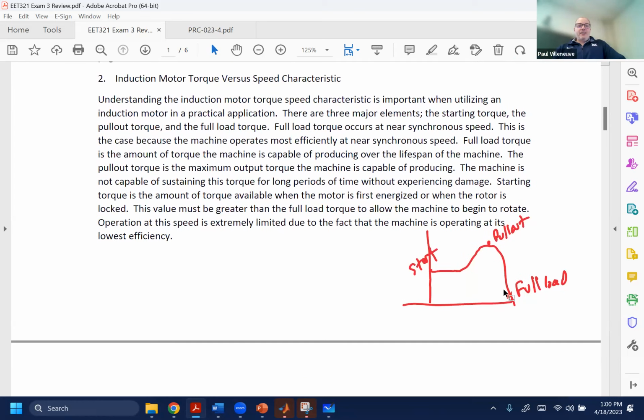So, yeah, questions on torque versus speed characteristics. That's the really important part, there are a bunch of different characteristics. We had P and Q. We know it's an induction machine, which looks like an inductor and a resistor. So is it always going to have a lagging or leading power factor? Let's see. It's a throwback from earlier in the semester. Does an induction motor have a leading or lagging power factor? Lagging. Lagging? Anybody want to agree or say leading?